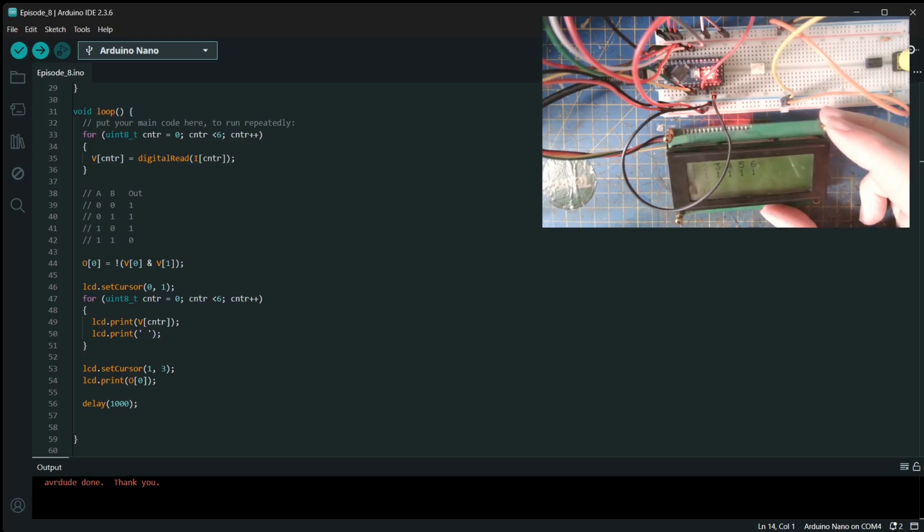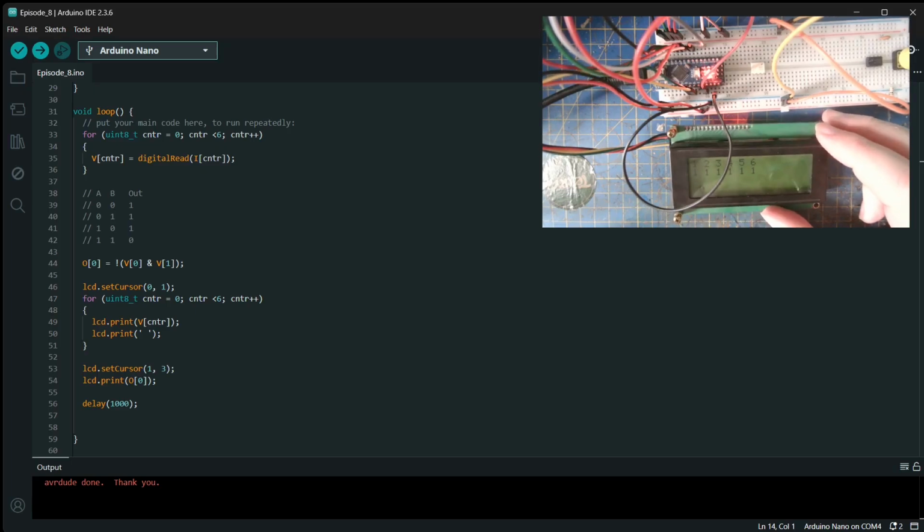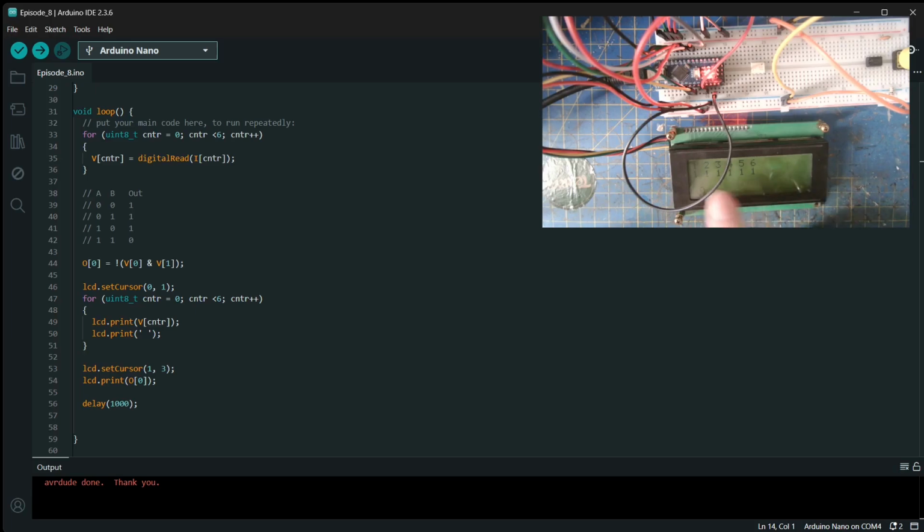We've seen the library, and we've seen how to write simple messages. The library does a little bit more. You can have custom characters. There is the data sheet for the controller chip. I think it's a Hitachi chip that's on the back of one of these things. It's got a character set, so you've got the basic characters you might expect, and then there's some other characters in it as well. I think there's a smiley face, and a few other bits and pieces. You've got, I think, 4 characters you can define yourself. So you can do a solid block and try to do a bar graph if you want to. If you're going to do that, use a different screen. It's just easier. These things are simple.